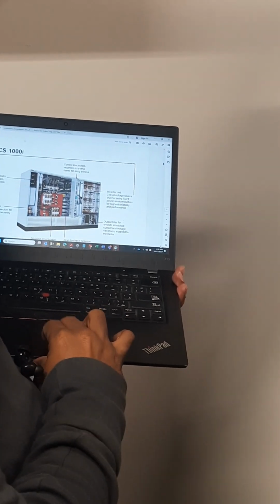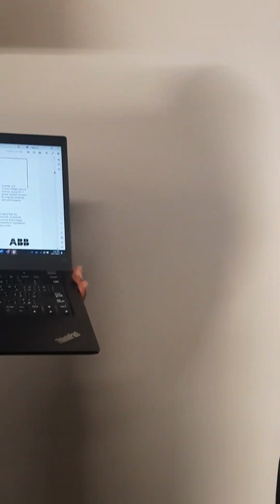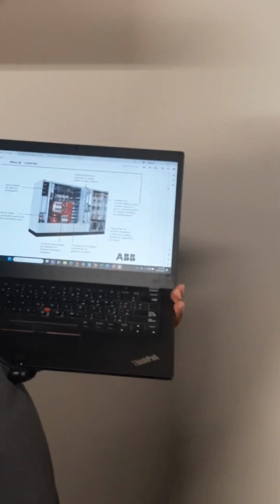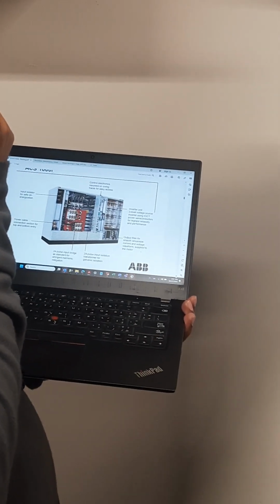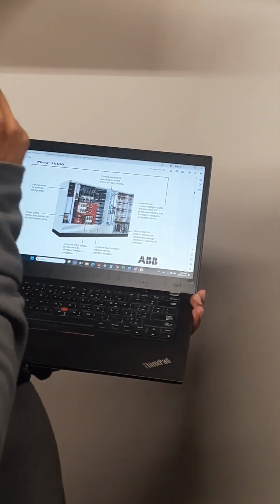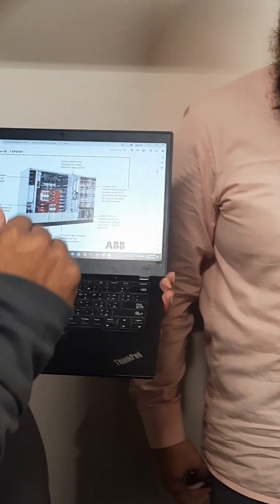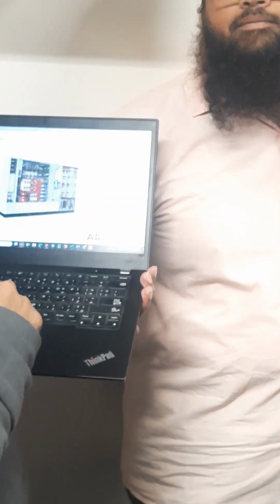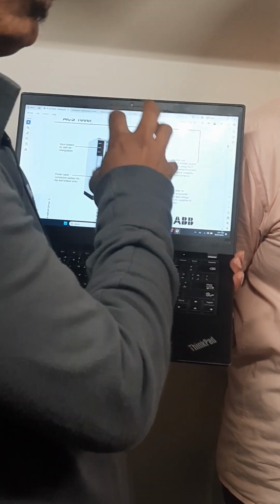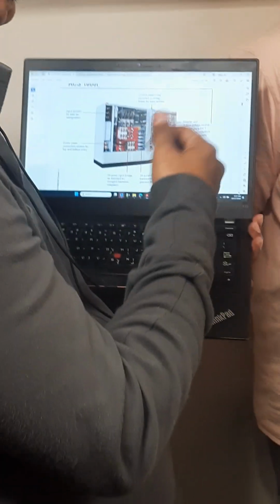One question now: this transformer has ventilation, correct? Are there any parameters to be maintained for the temperature inside? For example, if the room is getting overheated, there is a setting, so this VFD will trip in case of any overheating. Yes, because the drive is monitoring the temperature from the transformer also. The transformer side and inverter side are read separately.